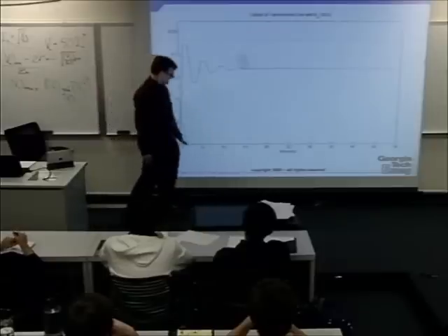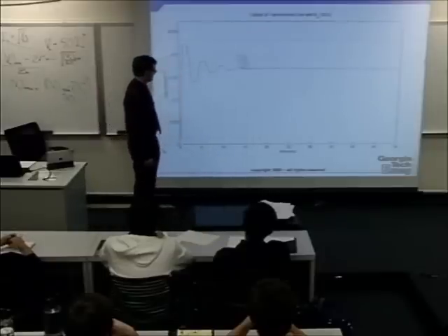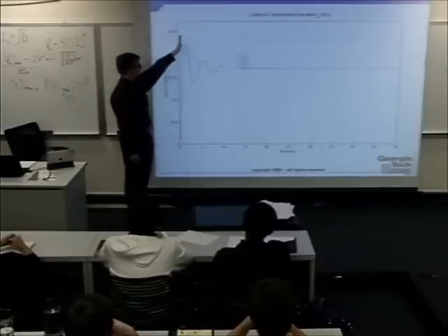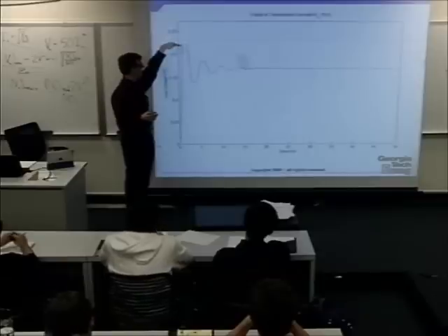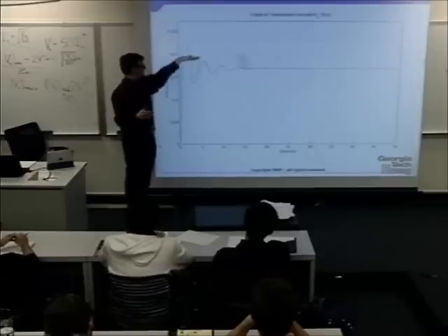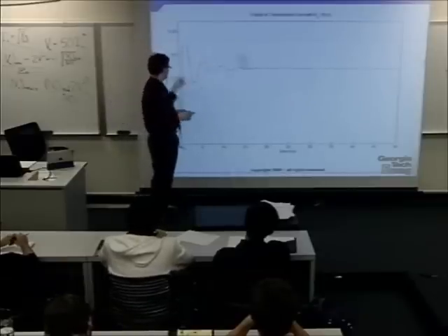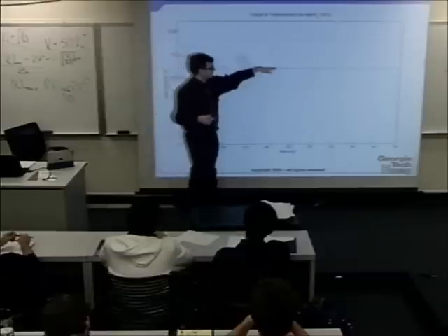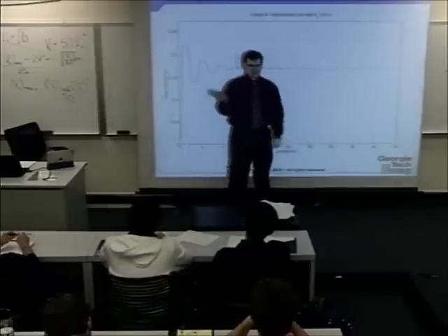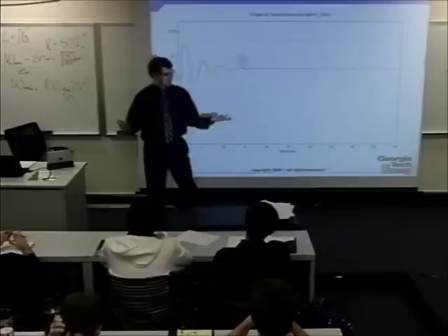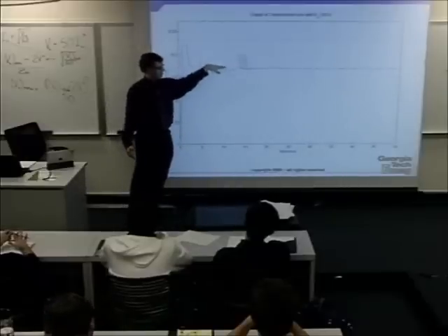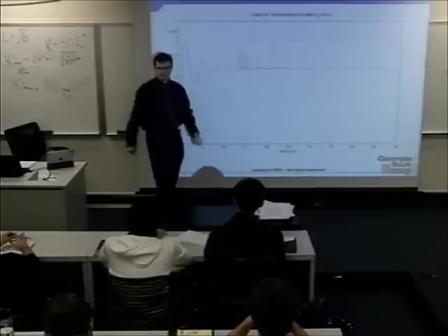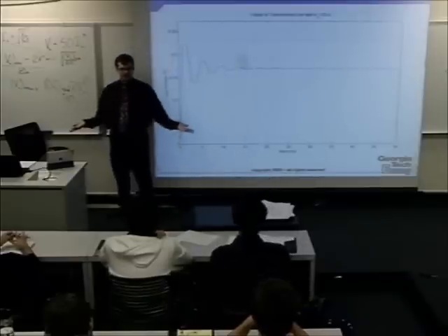So I have a time scale here that goes from 0 to 50 nanoseconds. We see the first strike at the end of the line where the voltage kind of doubles up. That diode's kind of looking a little like an open circuit or a large impedance. Then there are reflections through the system, and then it shakes out to about 0.18, 0.17 volts in the steady state. So it's kind of doing exactly what a resistor is doing, except these are not going to be very regular reflections. But you get to a stable point. Any surprises there?